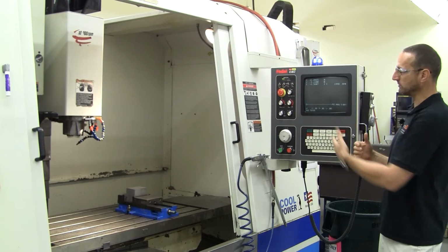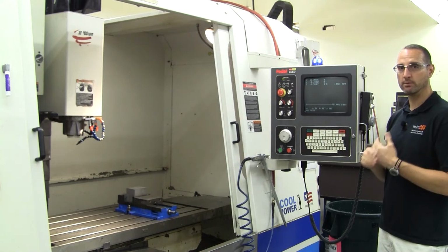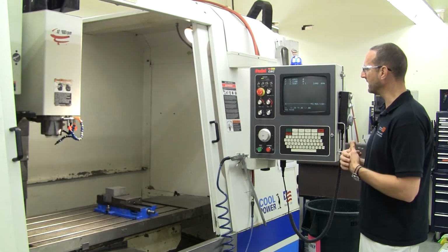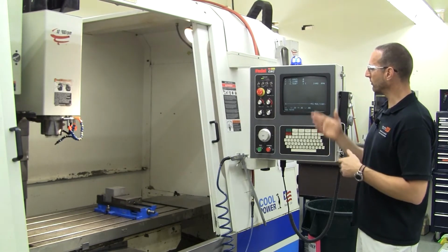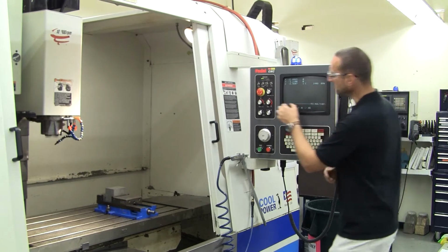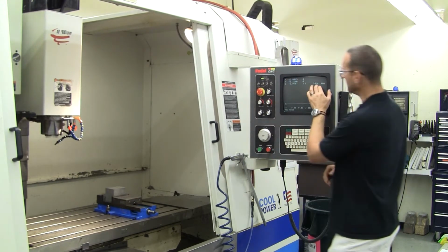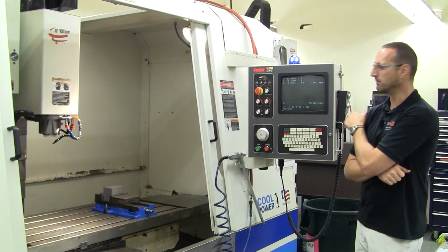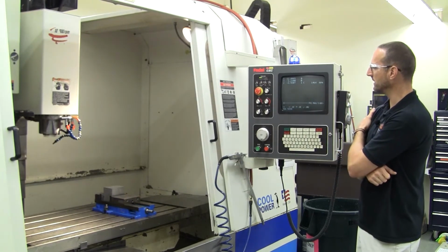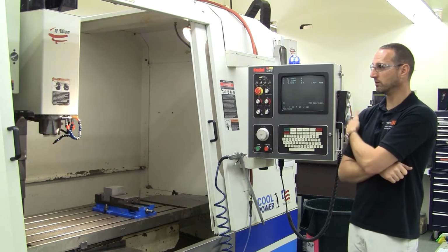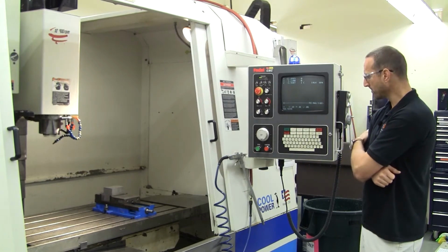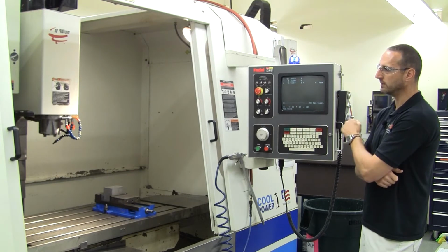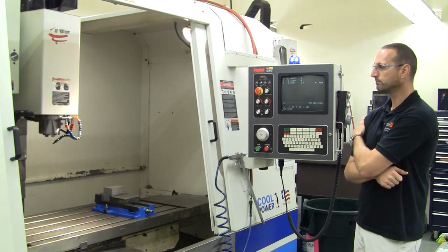So we did not run a program or go in MDI mode and set what spindle speed we wanted to run at in this particular case. Whatever program was run before was probably programmed to run around 1500 RPM, and we were just dialed down a little bit from there. So that's why the spindle is running at that speed. In order to turn it off, all I have to do is push the spindle off button, and then it'll stop spinning in the machine.